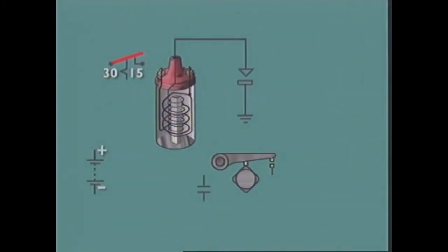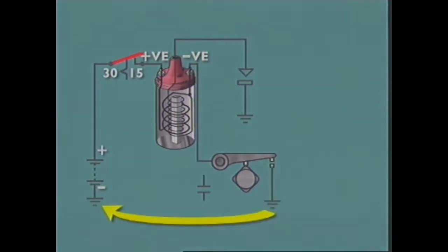In the primary circuit, the positive terminal of the battery is connected to the ignition switch, then to the positive terminal of the ignition coil. A connection is then made from the negative terminal to the contact breaker moving contact point. The fixed contact point is connected to ground at the vehicle frame, as is the negative battery terminal. This allows the circuit to be completed through the frame when current is flowing. A capacitor is connected in parallel with the moving contact and also has a ground connection through its retaining screw.